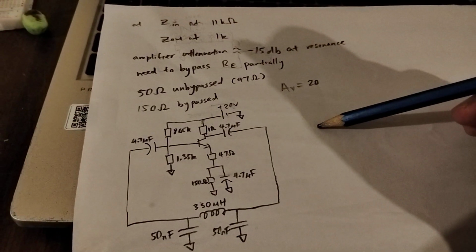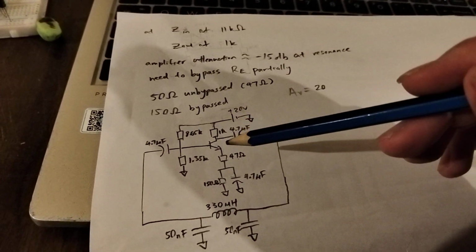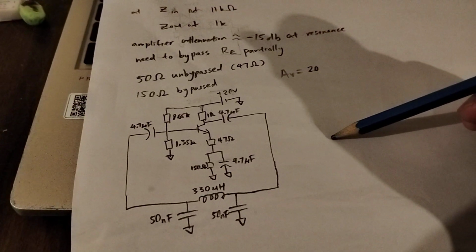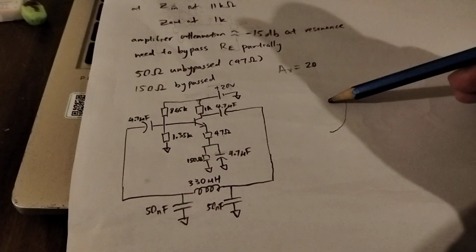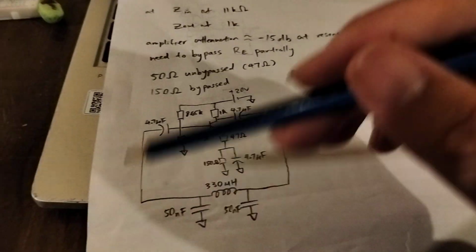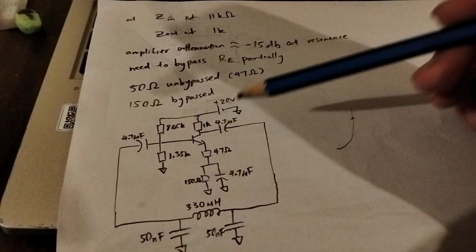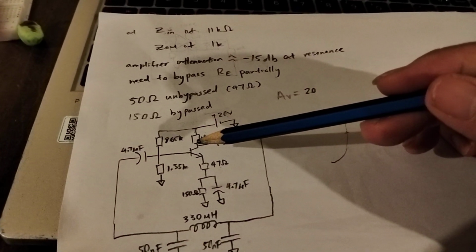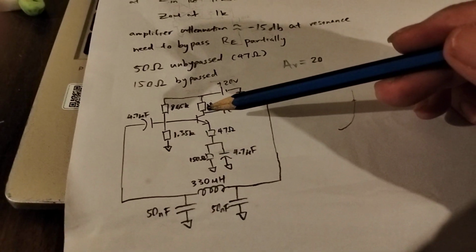So it's not a discrete shutoff like the way that an op-amp would be. Therefore, it doesn't clip the rails very hard. It's got a gradual clip, where at some point there's going to be a point where the gain is actually just 1 across the loop. And that's what's causing the gain control. It's actually using the gradual saturation and cutoff of the transistor to achieve this gain of 1.